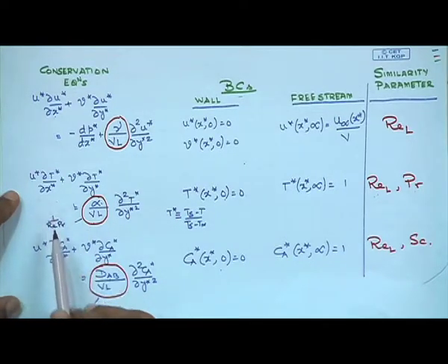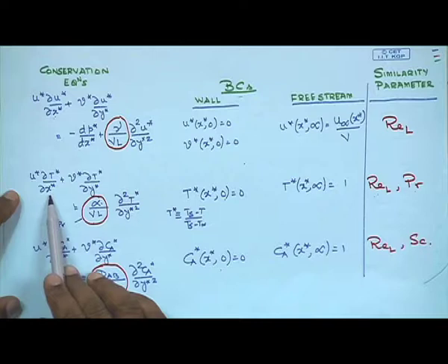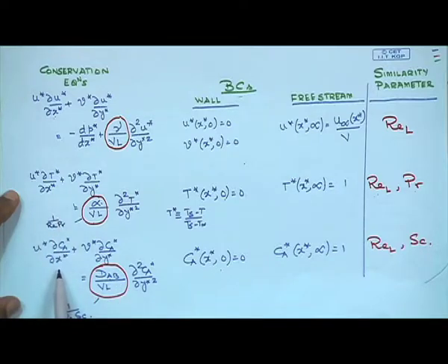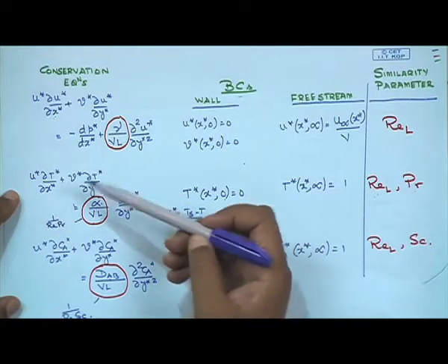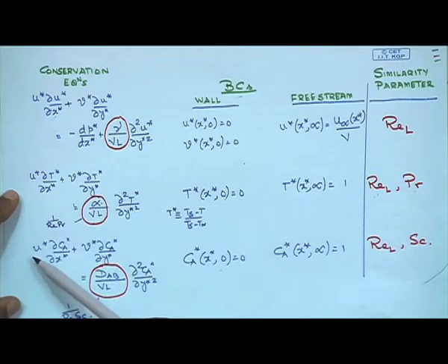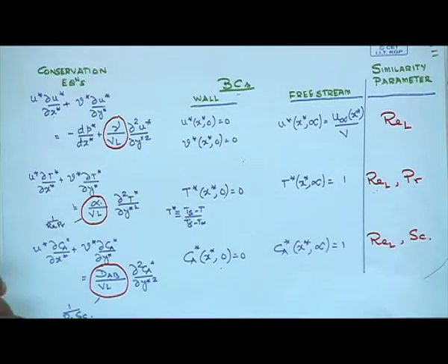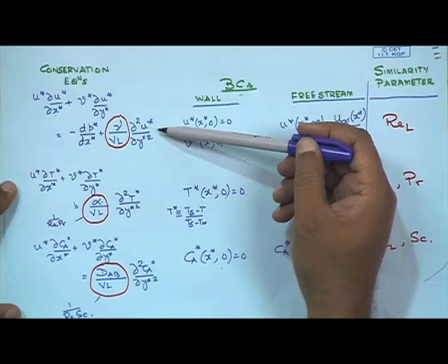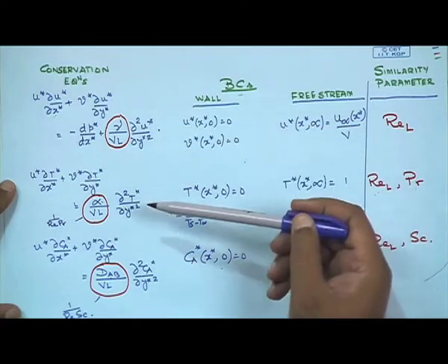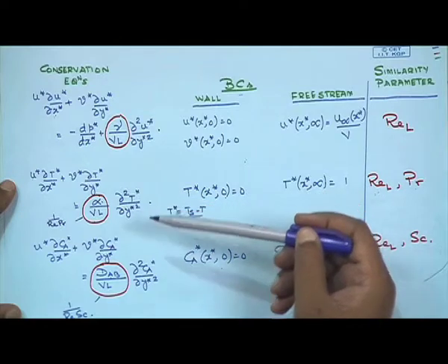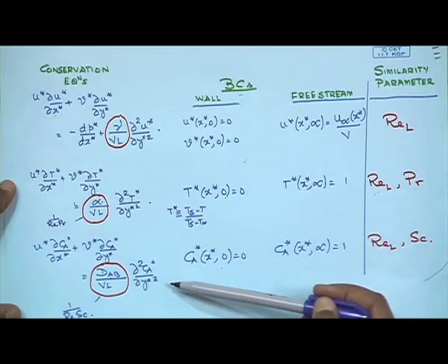On the other hand, if you look at the thermal boundary layer equation or the species boundary layer equation, you have the presence of U in both cases. So, in that way this momentum transfer can be solved independent to the solution of the thermal boundary layer or the species boundary layer.